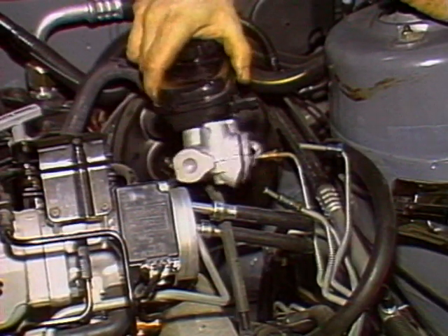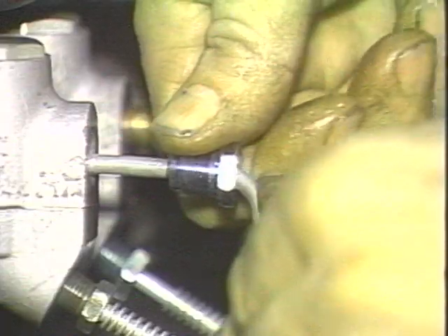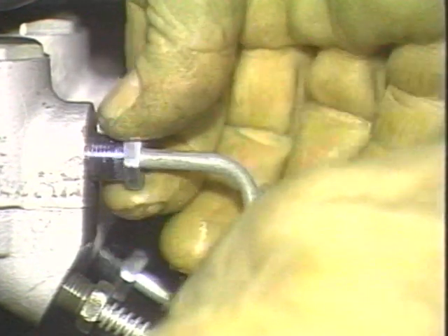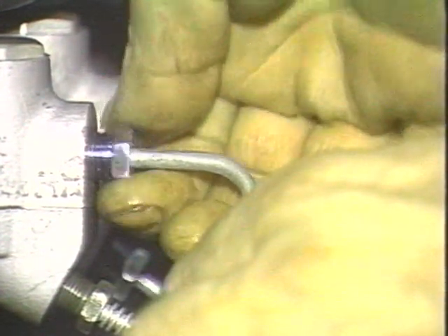Tighten the mounting nuts properly to secure the master cylinder in place. Then hand start the brake lines to prevent cross-threading. It is very easy to damage fittings and master cylinder threads, requiring time-consuming thread repairs or part replacement.